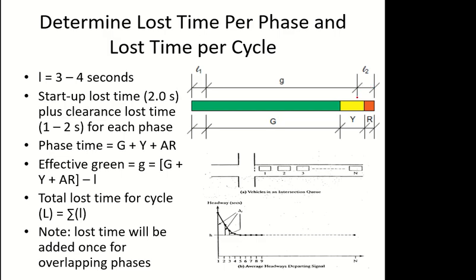Okay, so you stopped in the last second of yellow. You didn't want to take a risk that you crossed during red. And obviously there's a camera and all these things as well. Okay, so the all red time is part of L2, and the last 1 second, 1.5 seconds of yellow is also clearance loss time, because nobody is going inside.